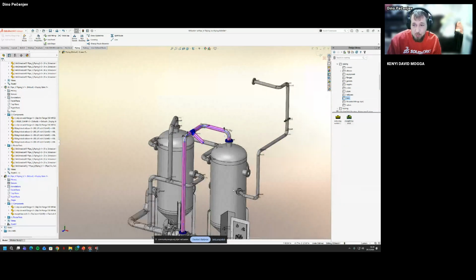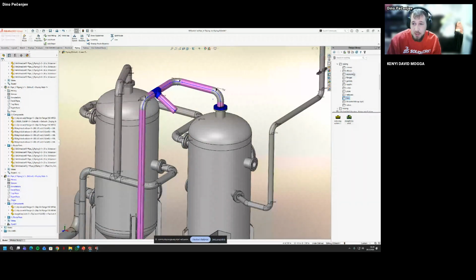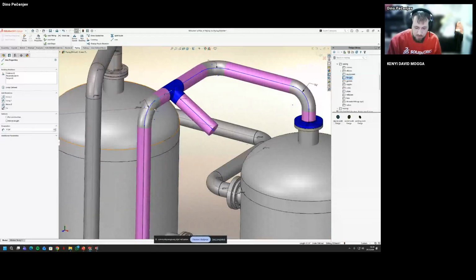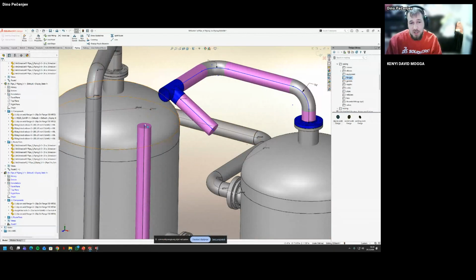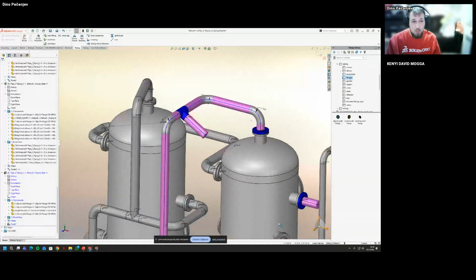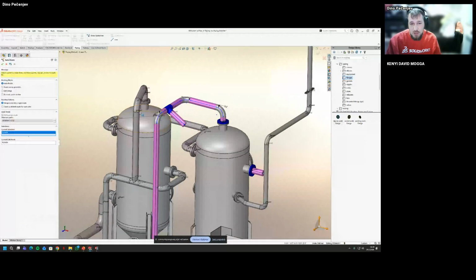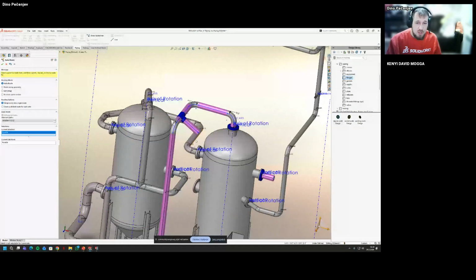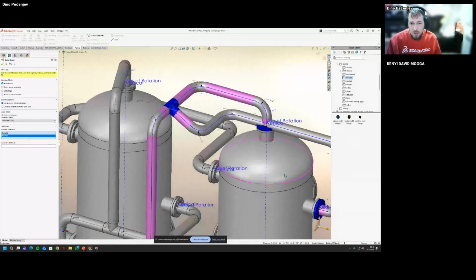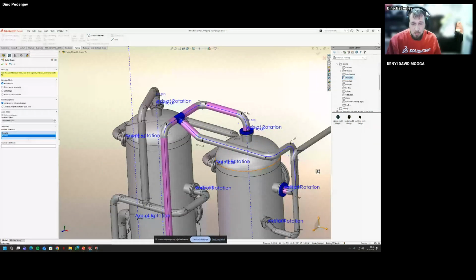And here we're done with this part, but I mentioned also the use of the function called remove pipe. So instead of removing this, what will happen? This will happen. I don't have an elbow, but I need to keep this elbow. So what we are going to do, I'm just going to finish up this. I'm also using auto route for this presentation because I'm focusing more on the techniques used here.